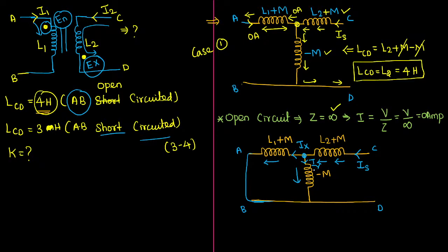In order to know that relation clearly, I am just injecting the current, and I also taught you this is the best effective way to identify the series parallel configuration relation. So here I clearly understood that this inductor L1 plus M and this minus M both will be in parallel because current will be divided. So now first estimate the parallel equivalent.